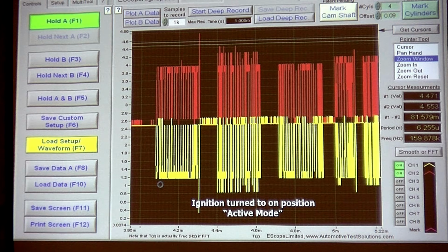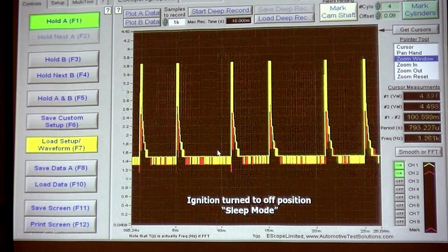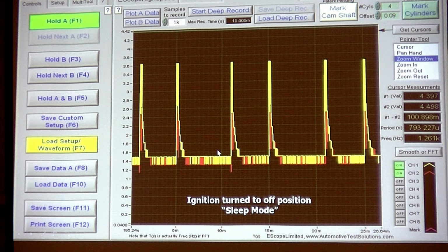So basically, this guy is active mode. This is sleep mode. So I've told everybody to go to sleep. When you shut it off, you'll watch the messages and they start to diminish. The way sleep mode is on the CAN transceiver, there's a 5-volt pin and they take the 5 volts off of it. That tells the transceiver that I'm going to sleep, so he tries to dump all his messages and finish up, and then you'll start to see it slow down.